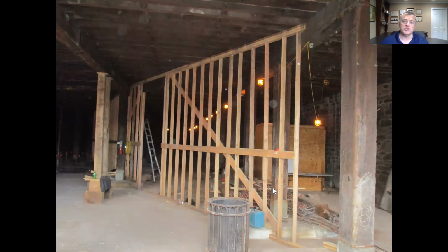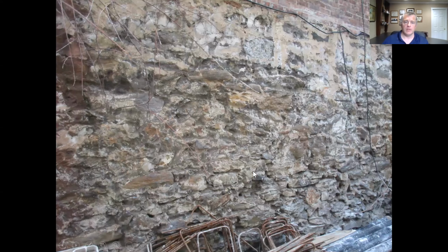You're going to see a lot of temporary structures be built. Again, we don't need to do this on new construction. We're just building. Temporary structures, structural engineer, architects say, yes, that's adequate to support that while we're replacing pieces. We're going to look at the condition of the rubble stone foundation wall. Is it in good shape? Do we need to parge it or patch it with grout or mortar?